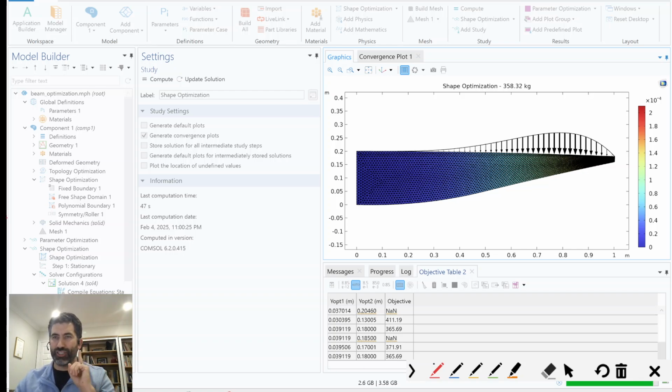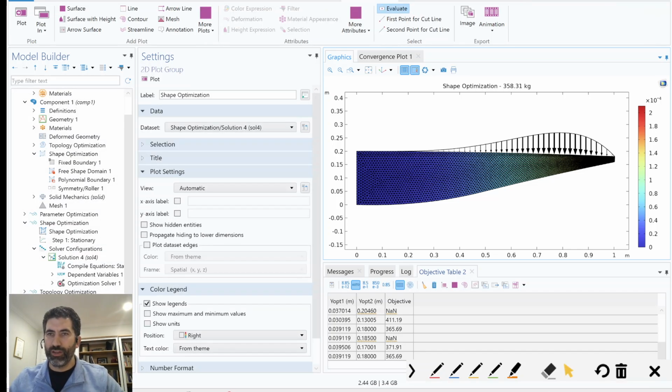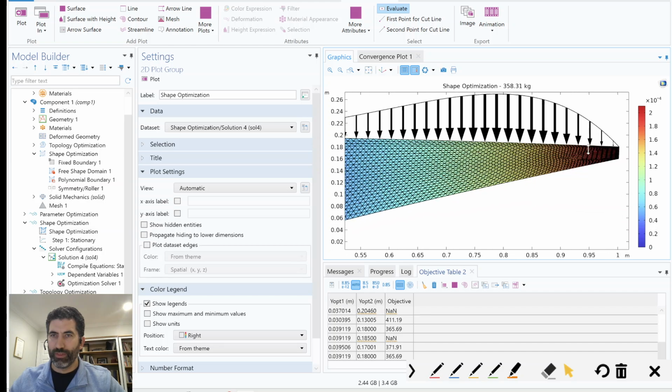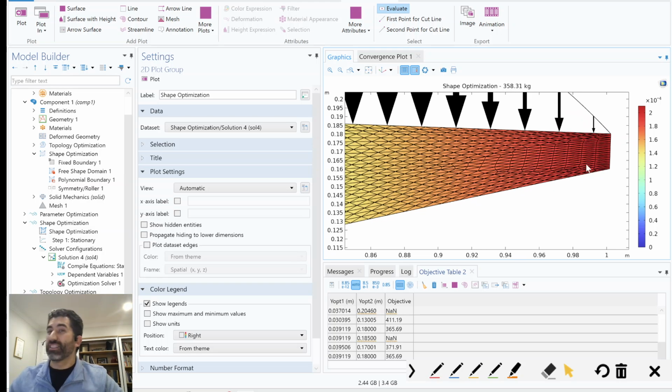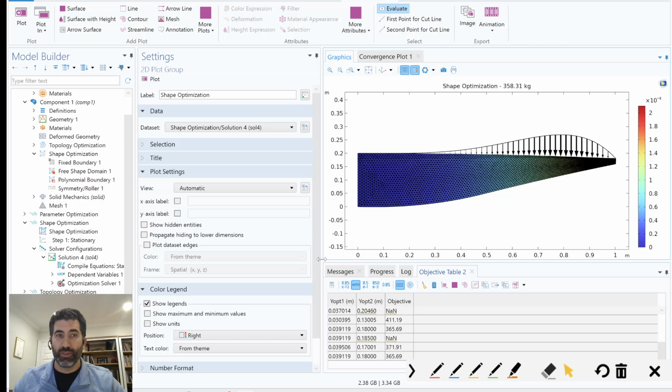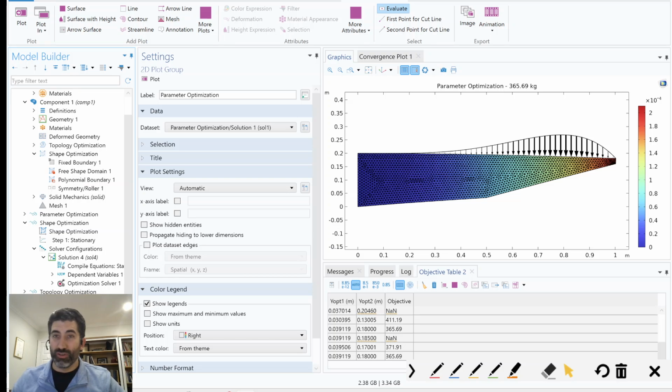The mesh hasn't changed, and that's important because when you zoom in here, you'll see that all of a sudden our mesh looks very different. It looks poorer quality because it is actually poorer quality. These thin elongated elements are inferior in terms of arriving at a numerical solution. But the benefit to this is that we don't have to remesh at every time step, at every iteration.